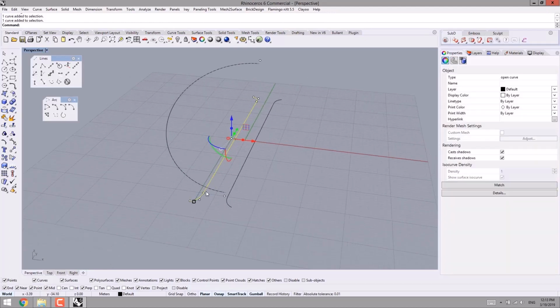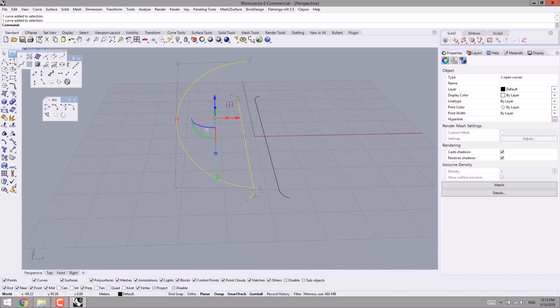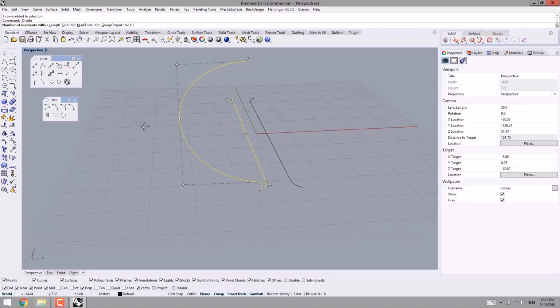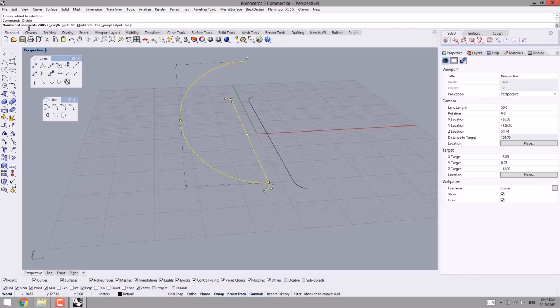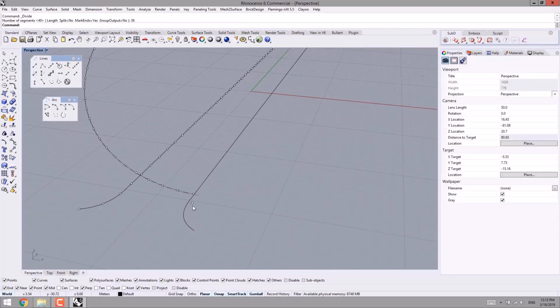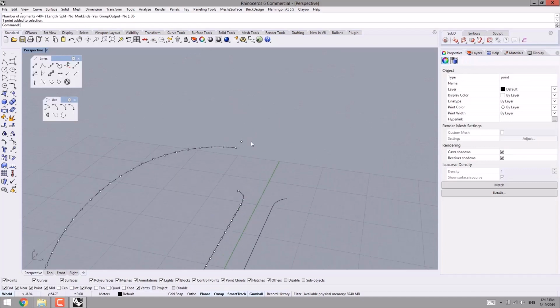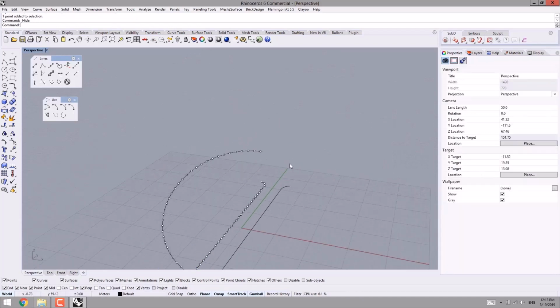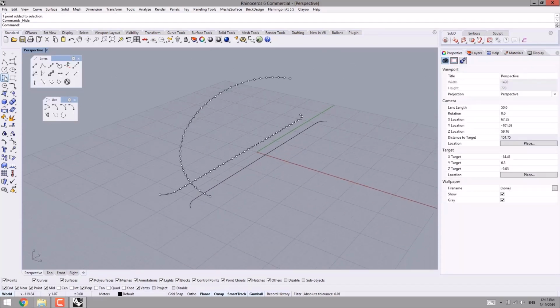So in the scene I select this arc which is joined, and then the arc. Then in the set of points tools, divide curve by length. I right click, actually divide curve by number. Then I specify the number of segments. Since I want the arcs to be divided based on the specified number, I type 36. Then the 2 points that were sketched according to the image, I select them and hide them with Ctrl H. They are not required.